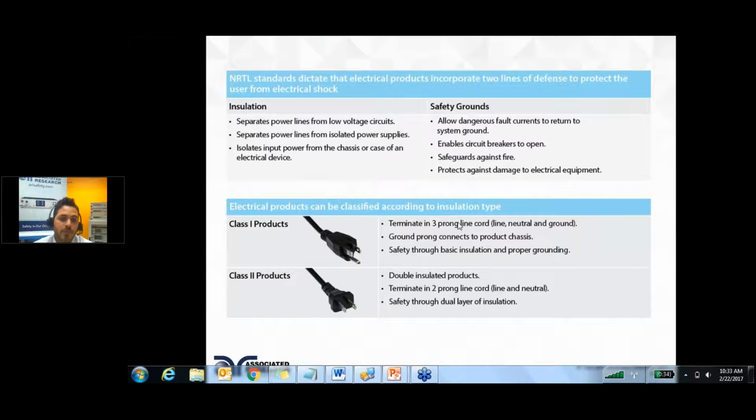But what does that mean? There's no definition of breakdown in standards, so the onus fell on the hipot testing companies to identify what a breakdown is. A breakdown is pretty much when our instruments see a short through your insulation. Once there is a short through your insulation, I know there's definitely an issue with your insulation, a huge hole.